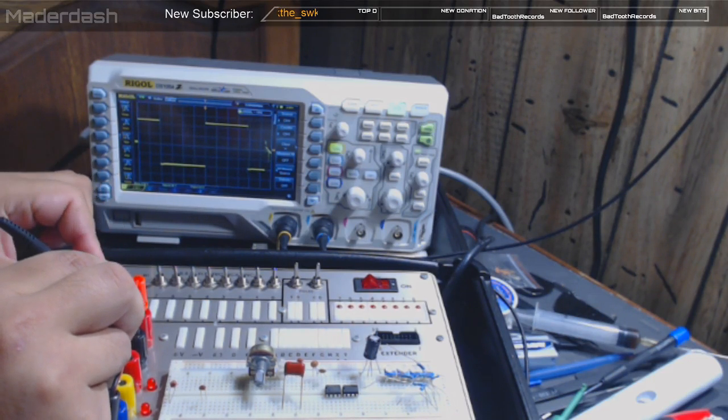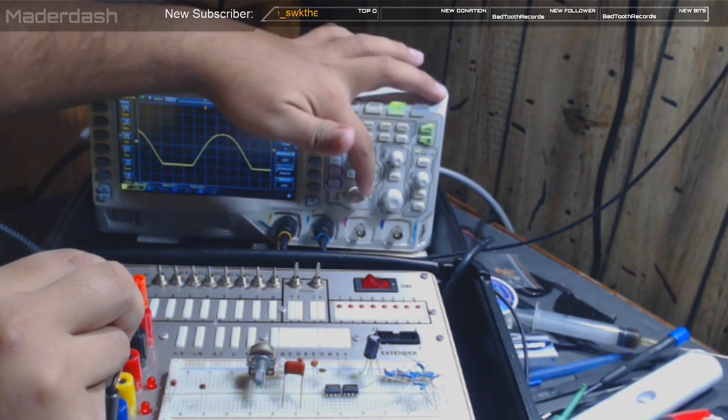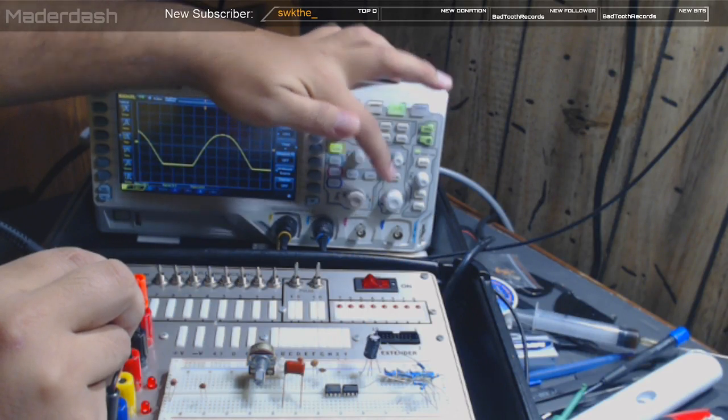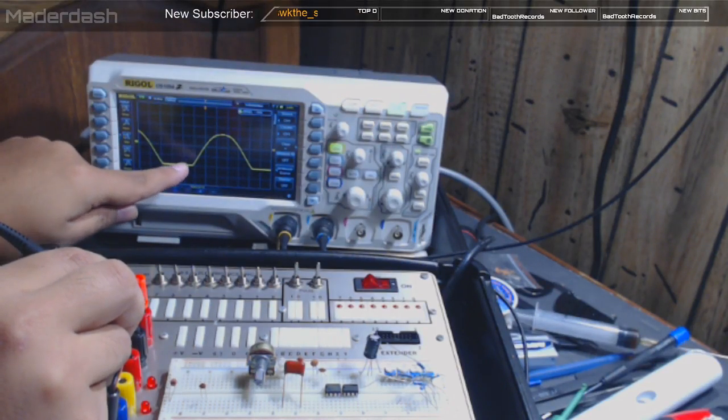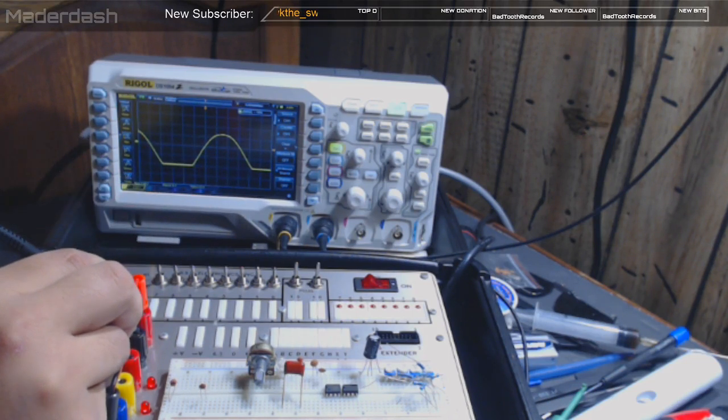But it needs a little bit of work. Right, there's a sine wave generator, and it looks like a transistor's weak or out because the top half looks nice and clean, as you can see, but the bottom half is a little bit clipped out. So the top half, the pull side, is working fine, but the push side is failing. So that's either a diode or, more likely, a transistor that is failing. It's just clipped out, so that'll need a little bit of work. I'll have to take it apart for that.